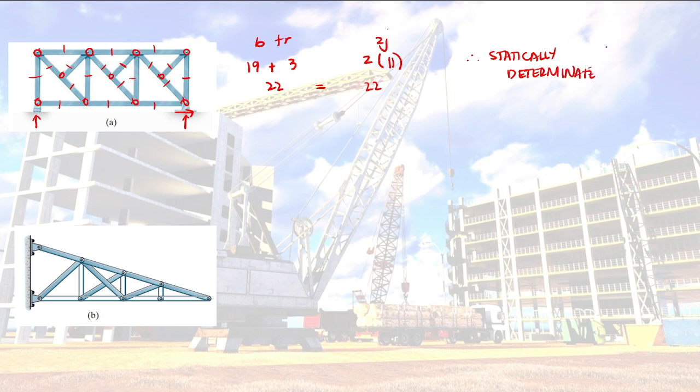Okay, another one, same, b + r, then 2j. How many bars? 1, 2, 3, 4, 5, 6, 7, 8, 9, 10, 11, 12, 13, 14, 15. 15 plus how many reactions? 1, 2, 3, 4.